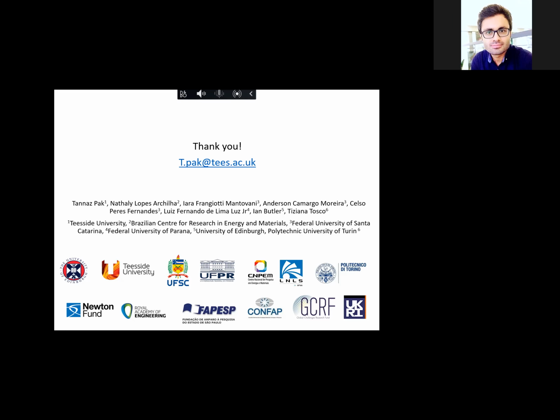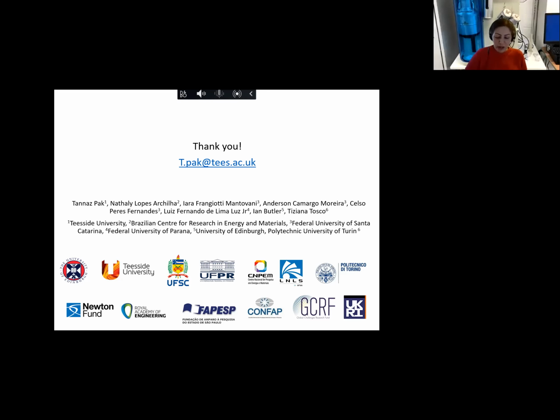Thank you so much for your presentation. You're welcome. I have a question regarding how you conducted the experiments. Did you have a back pressure for your microcore? Because we had this experience in Diamond Light Source that if we didn't have a back pressure, we could generate some water evaporation when X-ray hits the core. So I wanted to know, how did you make sure that this gas is produced due to the reaction, not the X-ray injection? Yes, very relevant question.